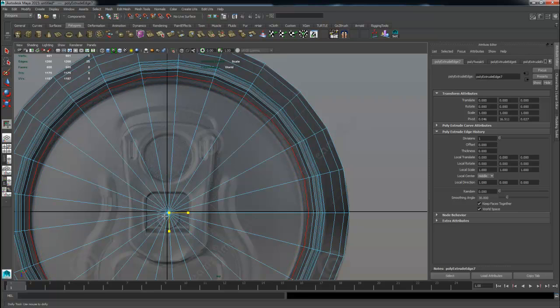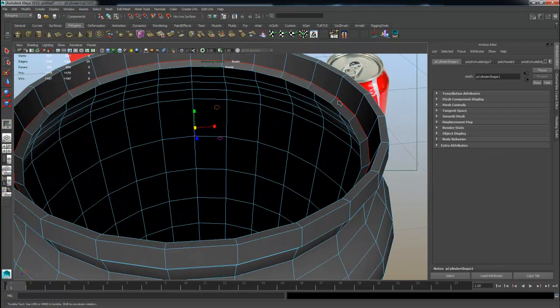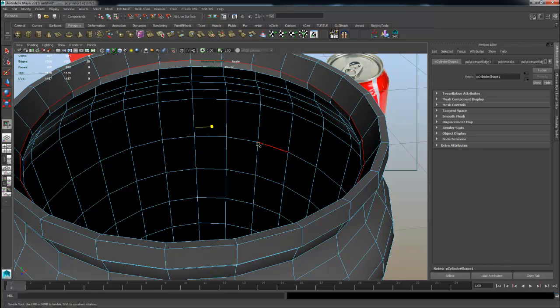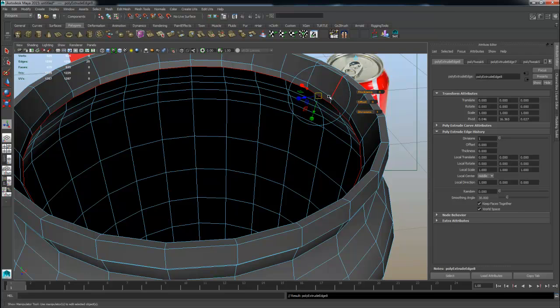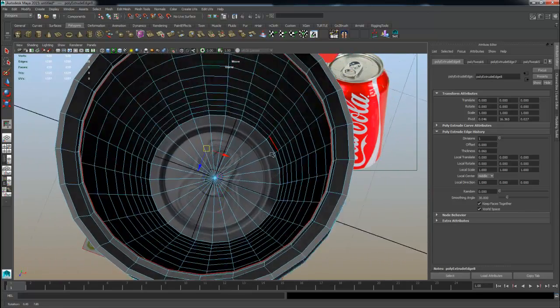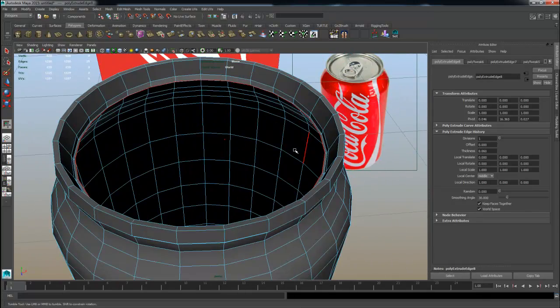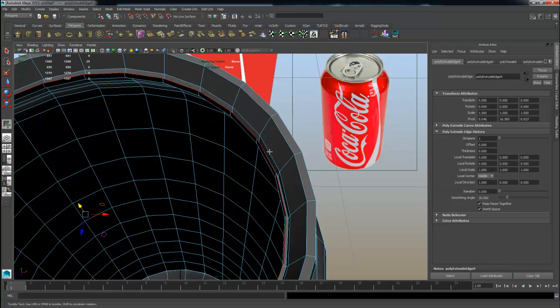I quite often follow this workflow. Instead of using the internal transformer tool of the extrude, I typically jump to my regular move tool, which is W on the keyboard, and then make my decisions on moving it based on a world position. After that, I'm going to use the internal thickness property for the extrude tool, and then kind of get that width of the bevel, doing another extrude, and probably start moving that up and over.